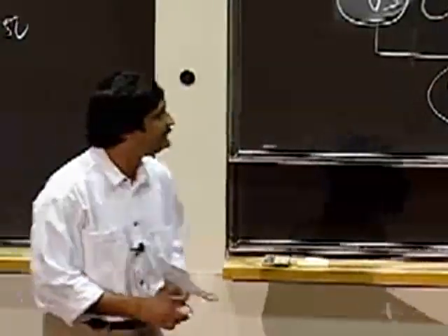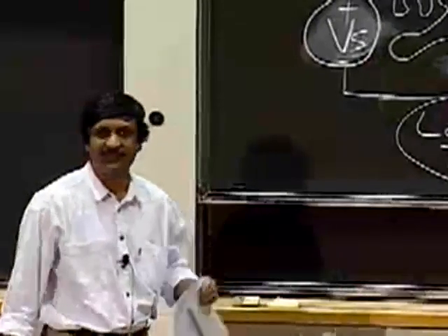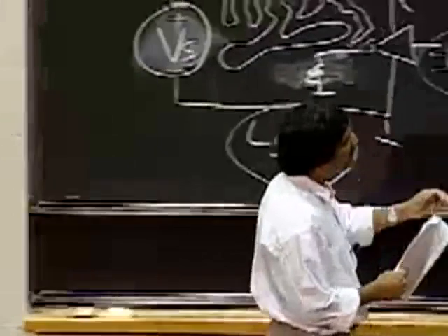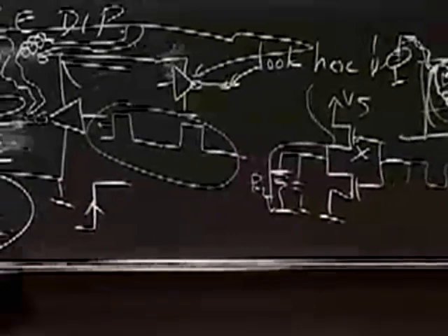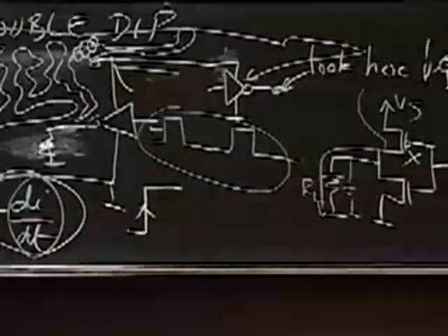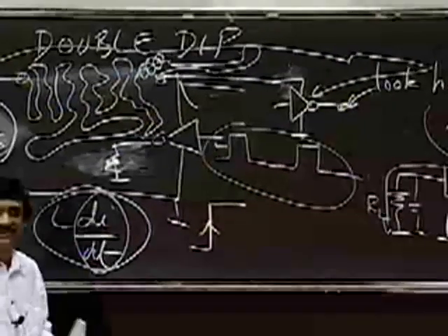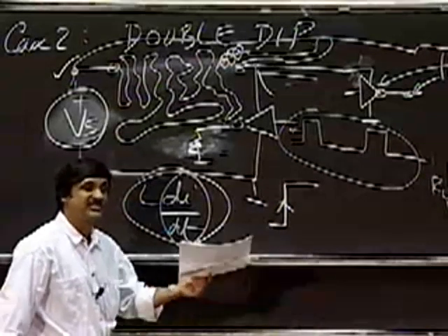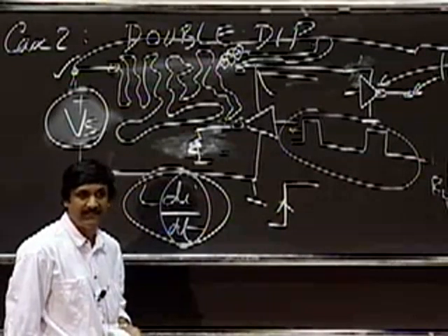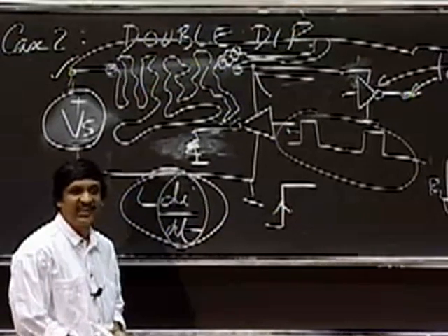There are other solutions, of course. There are a couple more solutions. One is this: part of the problem here is that all my transitions are really, really sharp, so dI/dt is very, very large. There's a whole new technique in the design of digital and analog circuits, maybe I should call it waveform engineering, or edge engineering. It's also called edge smoothing.